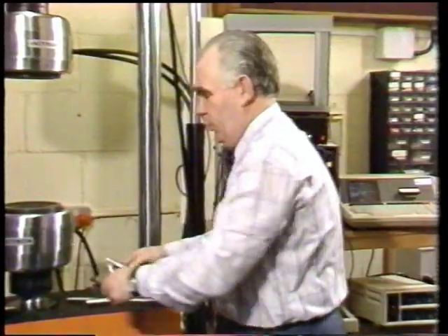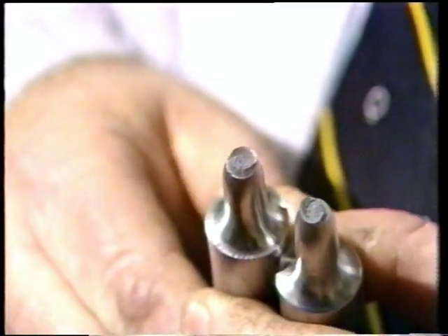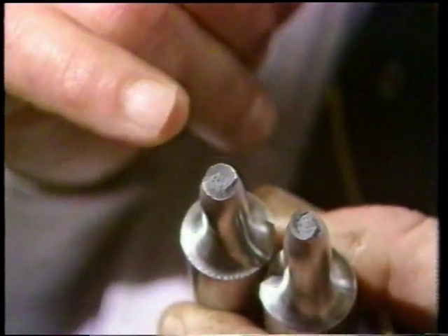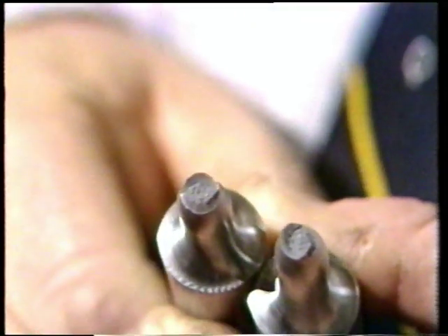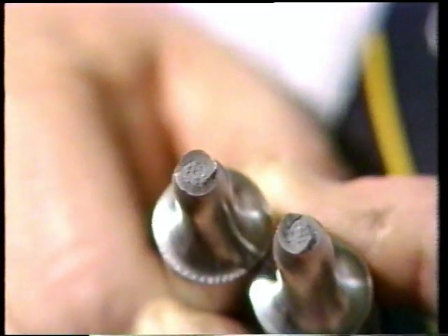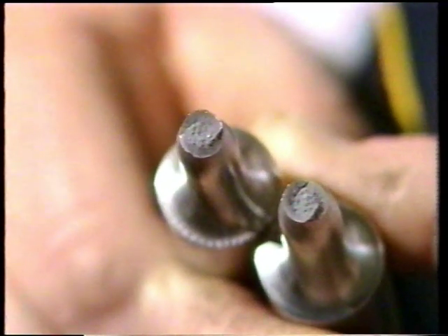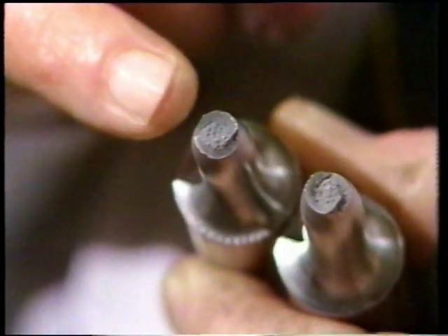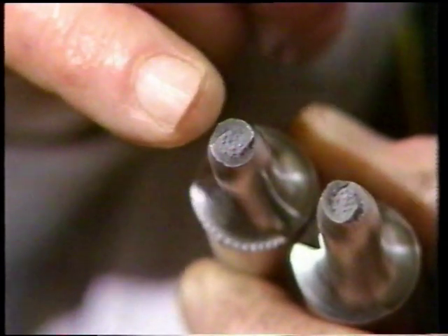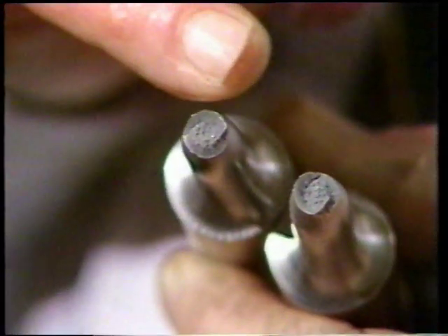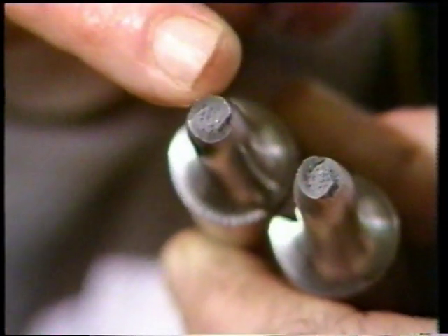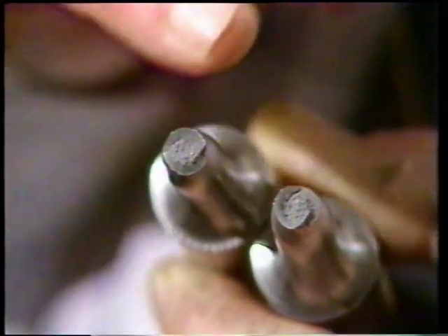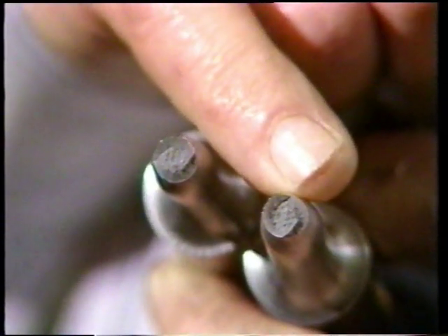Now, when this test piece fractured, it occurred in two distinct stages. The first stage of fracture is a crack deep within the neck at right angles to the axis of the specimen, which gives rise to a flat fracture. But then as that gets toward the outside of the neck, it changes direction and becomes 45 degrees shear. And so the outside is a 45 degree shear lip. On this particular test piece, half the lip is on this side of the fracture and the other half is on that side.